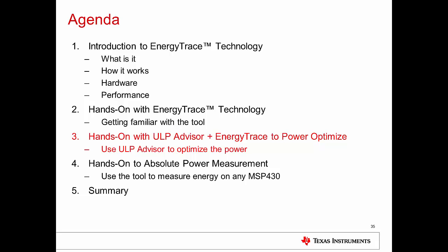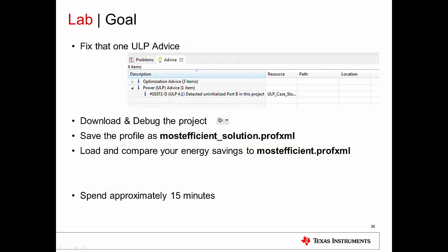Now that we have familiarized ourselves with Energy Trace, I want everyone to do a little exercise on your own, which leverages ULP Advisor to optimize your energy consumption while using Energy Trace. Earlier, there was one ULP advice remaining in your system: an uninitialized port B in your project. The goal here is to fix that one ULP advice